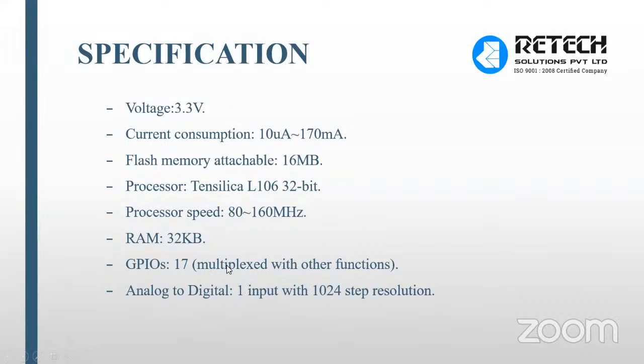If you want to interface two or three analog sensors with this microcontroller, you definitely need the MCP3008 IC. With the MCP3008 IC, we can interface two or more sensors with the ESP8266. But if you are using only one analog sensor, we do not need the MCP3008 IC. Based on this microcontroller, we can easily read the data.